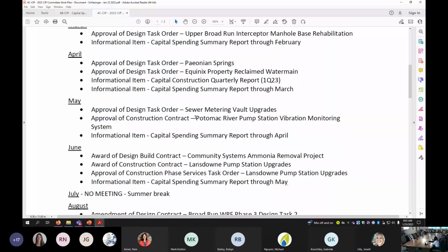Have we ever figured out what was wrong with that pump? We don't have a smoking gun necessarily, but we were able to resolve it by addressing various things. We changed the line shaft bearing material. We think that probably had the most to do with it, but we also made a couple of operational differences in terms of how we run the pumps, and we also hardened the shafts so that they're harder to erode.